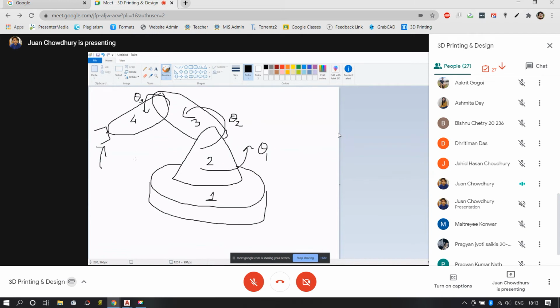Because I'm modeling each part differently, when I put it in the 3D printer, the time consumed for each part will be less than if I had printed it in one go. Because of power constraints and material constraints, you have to keep in mind that once you have started the print, if you stop in between, there's no going back. You just cannot stop and restart in place again. The part gets destroyed in most cases, unless it has a specific mechanism to revert the process.